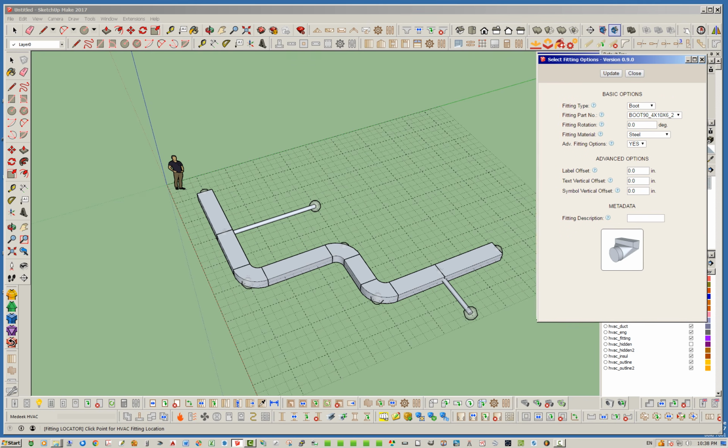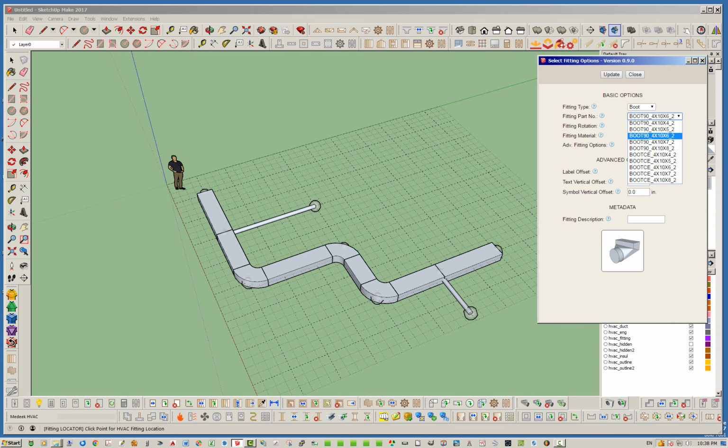When you click the fitting tool, which is this one right here, draw fitting, you will have a little preview screen showing you what your fitting looks like. I obviously need to add a bunch more; I've just barely started adding them in. I will go into the part numbers later, but basically you start with the style of the boot, then the register dimensions, and the last dimension is usually the diameter of the round pipe. For instance, this one here is a 6-inch pipe.